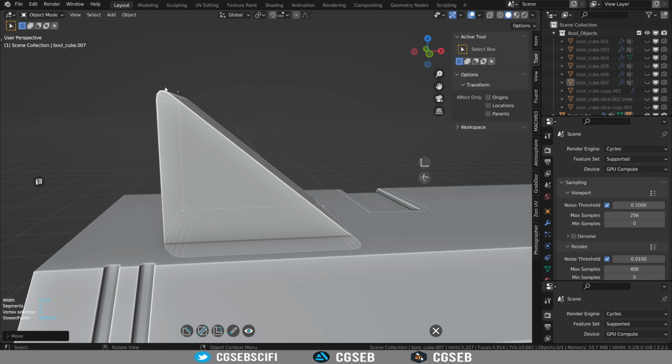The problem is that it's adding a bevel to all the corners. So to fix that, we're going to go to the left, press X. So now none of the corners are selected. And if you go closer to this one with your mouse and then press X again, you're going to be able to adjust just this one. So I'm going to make something round.